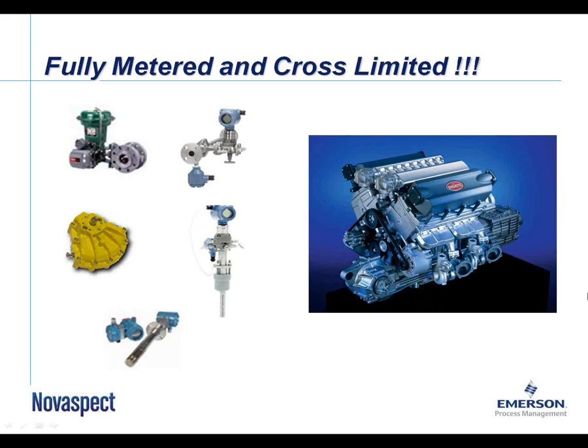And this is not just gratuitous advertising on our part, although it is what it is. I also wanted to put these loops up here because many times when we're getting ready to do combustion tuning, people will say, what do we need to do to prepare? Well, the one thing I really insist on when I start combustion tuning is knowing that the O2 meter has been calibrated recently. There's nothing worse than setting your fuel and air curves up to make the O2 meter read the right value, and if you go through all of that and a week later the customer does his yearly PM on the O2 meter, changes the cell, and then you realize that we set the curves up to the wrong value. So that's probably the most important one.